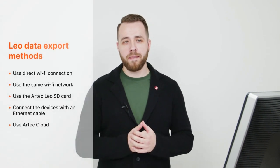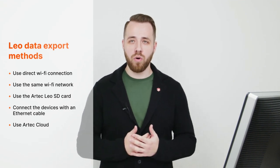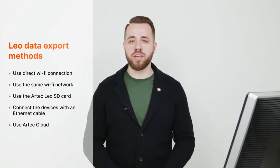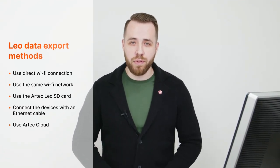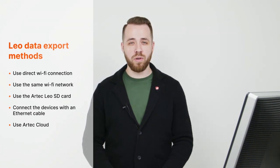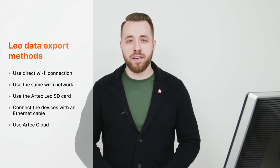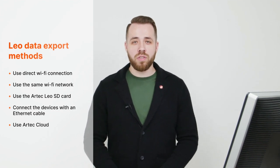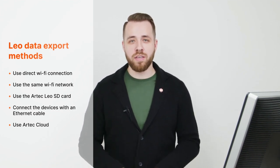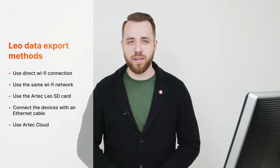When we're done scanning, there are multiple different ways that we can go if we need to import data to a computer. So generally, we have four options. The first one is establishing direct Wi-Fi connection between the scanner and the computer. The second option is to place both devices into the same Wi-Fi network and send the files like that. Option number 3 is to use an SD card, memory card that is inserted into the Leo. And the last option, which we will use right now actually, is sending your files via the Ethernet cable. This is the quickest method, so we'll use it right now.